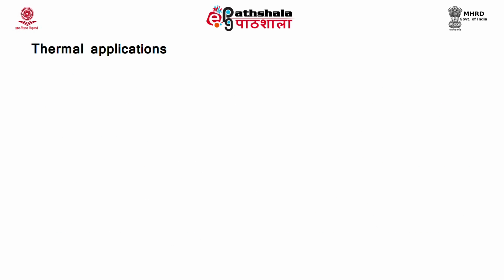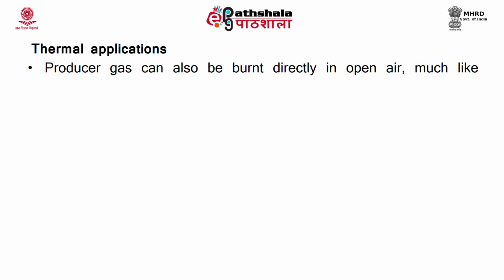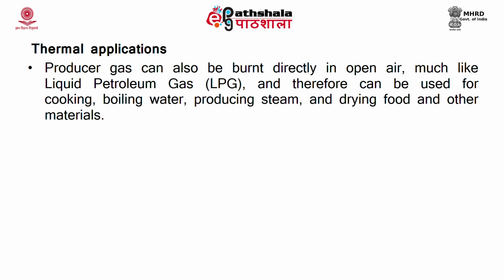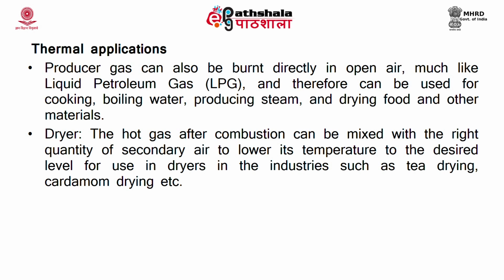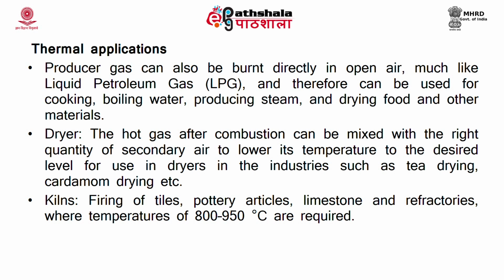So, the applications of gasification are thermal or power. The producer gas can also be burned directly in open air and it can be used for cooking, boiling water, producing steam and drying food. So, it can be used in a dryer. Here the hot gas after combustion can be mixed with the right quantity of air to lower its temperature and to dry things, for example tea drying, cardamom drying, etc. It can also be used in kilns, that is brick kilns, firing of tiles, pottery articles, limestone and refractories.